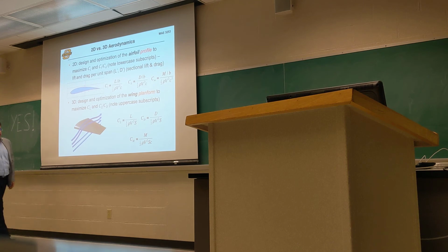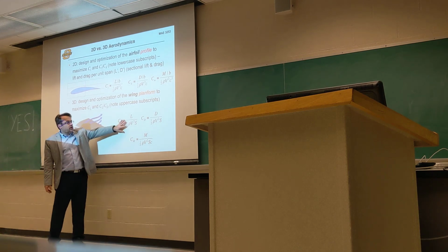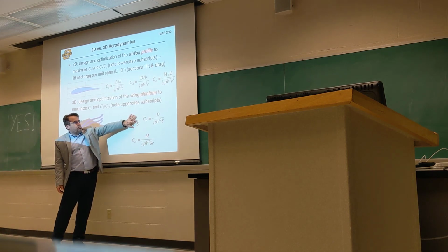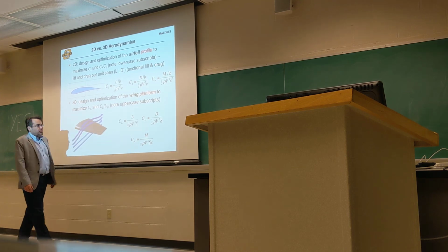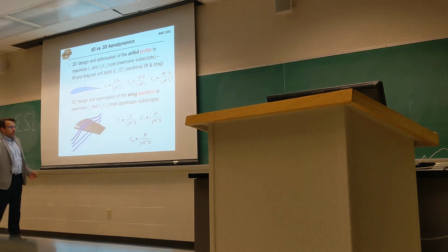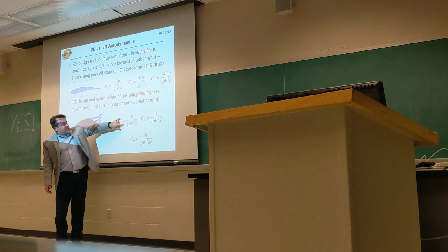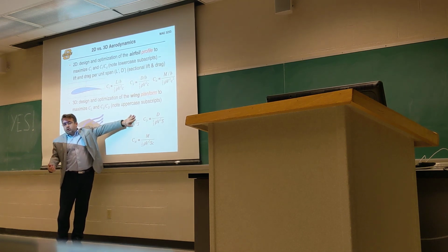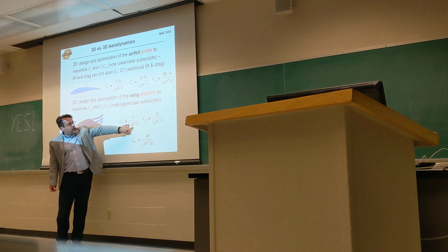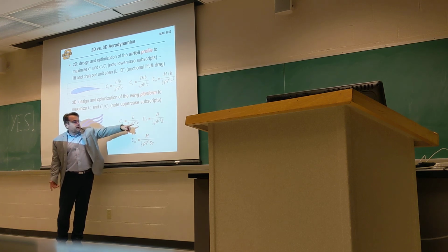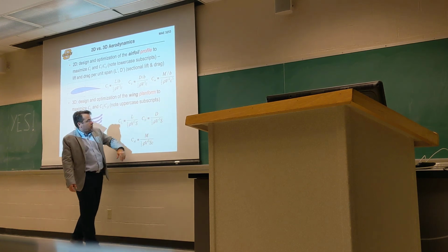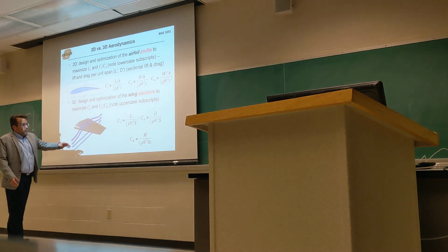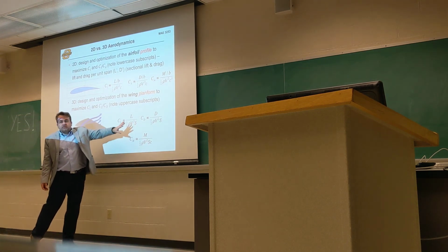This is not only how we did it traditionally and historically, but this is the more practical approach, because that's what we want to be able to get, is define that, right? So our lift coefficient is a definition based upon how much lift your wing is generating at a given dynamic pressure for a given area. Likewise for drag and for moment. Right? And remember, these are dimensionless values.